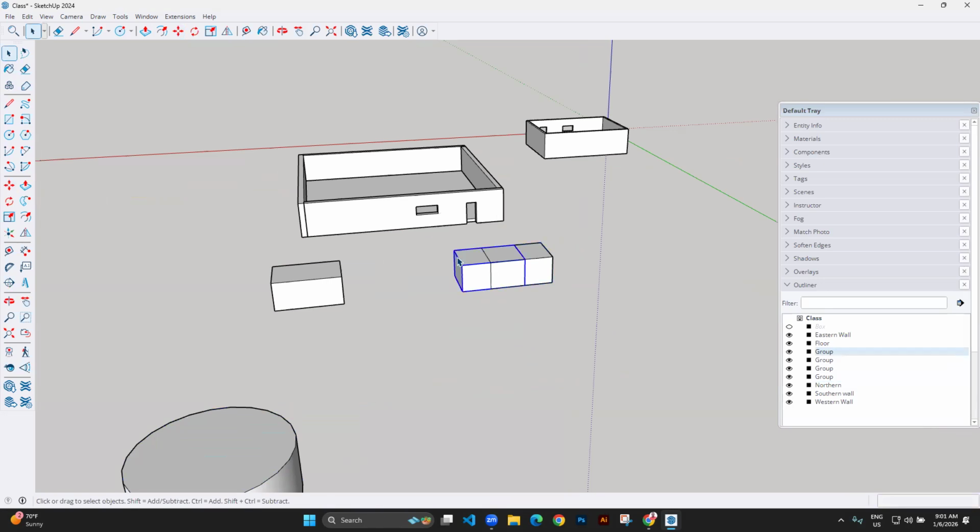But what if I'm copying the same thing, but this time around I base here and I still say 2 meters. I press enter. You see, the destinations are different. Let me do when the distance is big. Let's say 5 meters. You first press Control so that it leaves a copy behind, then you can put in 5 meters. That one is 5 meters apart from here. What if it's 5 meters, but I'm basing here?